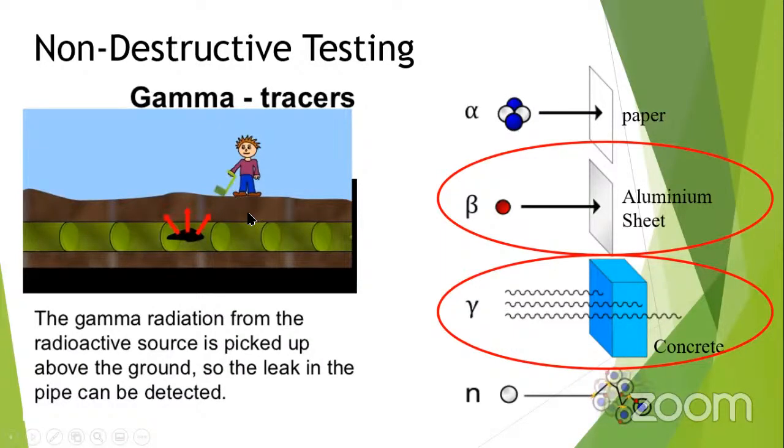All right. So how to detect? Basically, if there's a water source here, we inject it from here. Then of course it will follow the flow. If there's a leakage here, water will come out. If water comes out, it means the radioisotope or the tracer will also come out. So it means that at this spot we can detect a very high level of radiation. All right, then this spot no longer has radiation, maybe a bit, but not significant anymore. All right, but we know that when it leaks out, we can detect more radiation here.